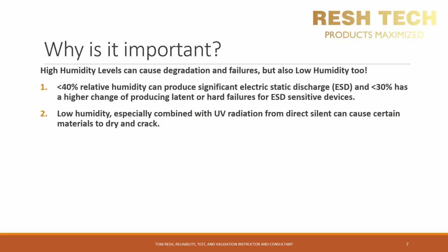Low humidity levels create the ideal conditions for higher electrostatic discharges to occur. Electrostatic discharge, or ESD, typically occurs when a person becomes positively charged and comes within close proximity of an object that has some level of negative charge. The electrons from the negatively charged object flow to the positively charged person until the positive and negative charges balance out and come to equilibrium.